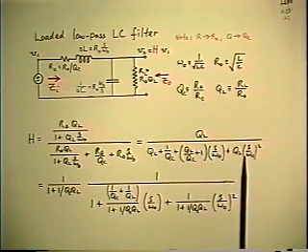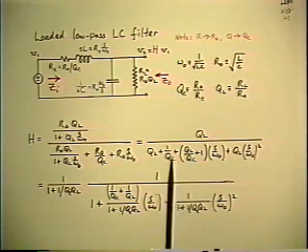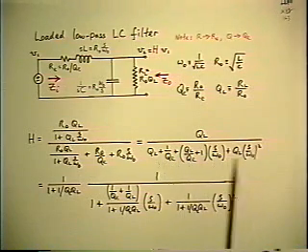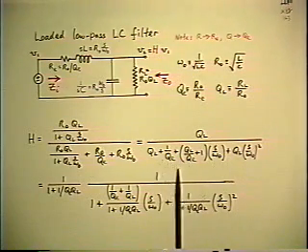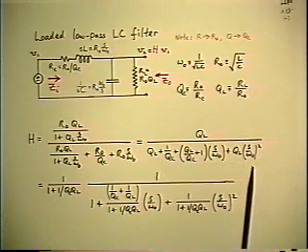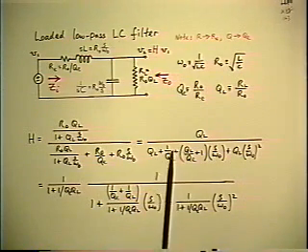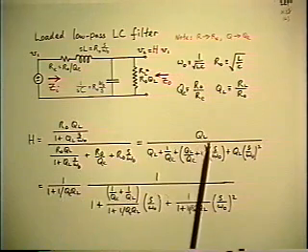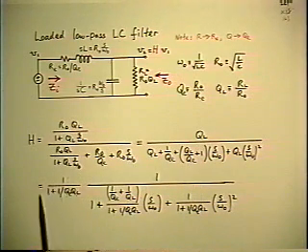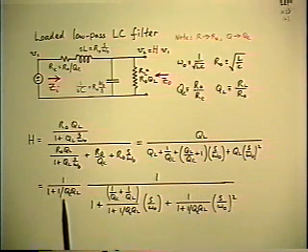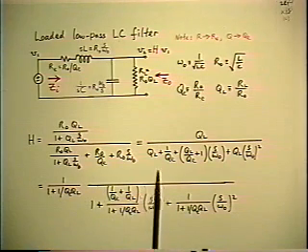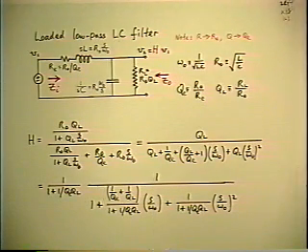And the final step is also the usual one. You'd like to make the polynomials have a leading term of 1, so you can identify corner frequencies. So in the denominator, you bring out the constant term, do the same in the numerator, that develops a ratio again. And now you're left with a ratio of two polynomials, both with a leading term of 1. So this is the standardized or normalized form of the result.